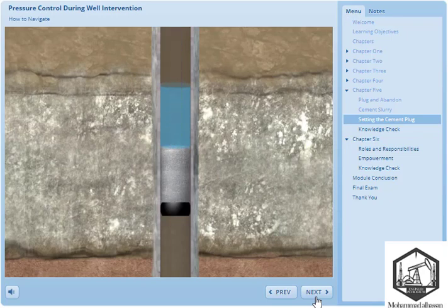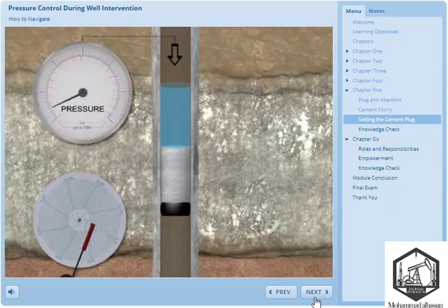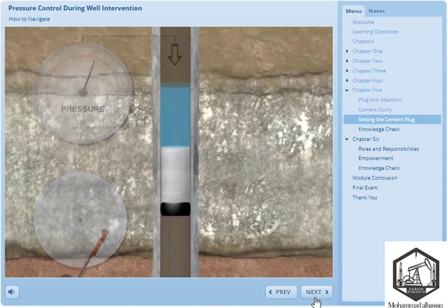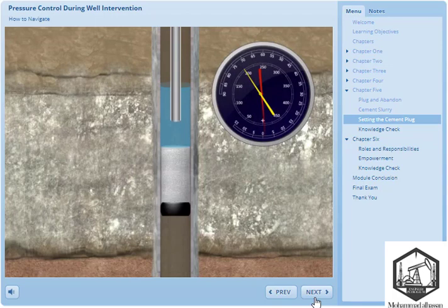After sufficient time has been allowed for the cement plug to set, it must be pressure tested to check integrity and checked that it is set at the correct height. This is usually done by tagging the cement, measuring where the top of the cement is, probably using the same tubing that the cement was pumped through.